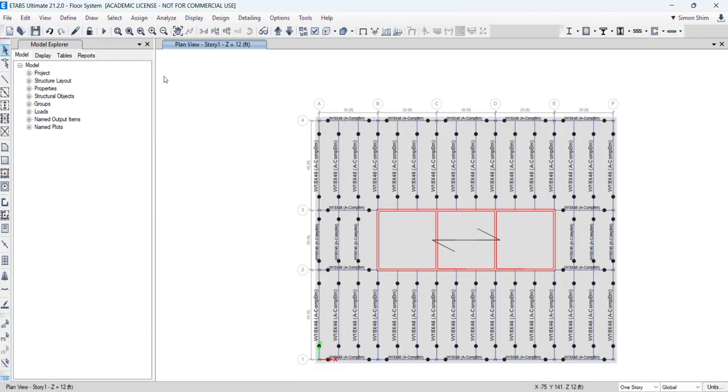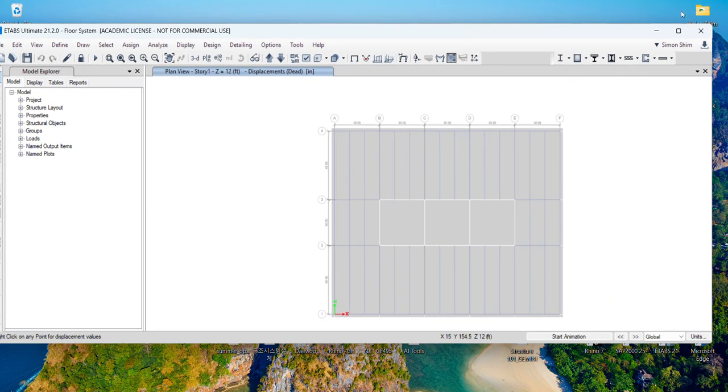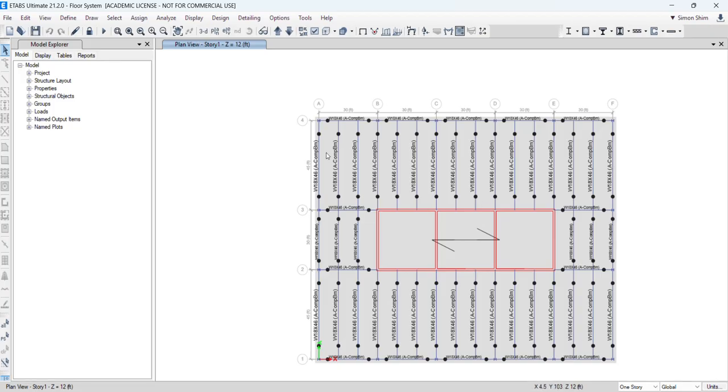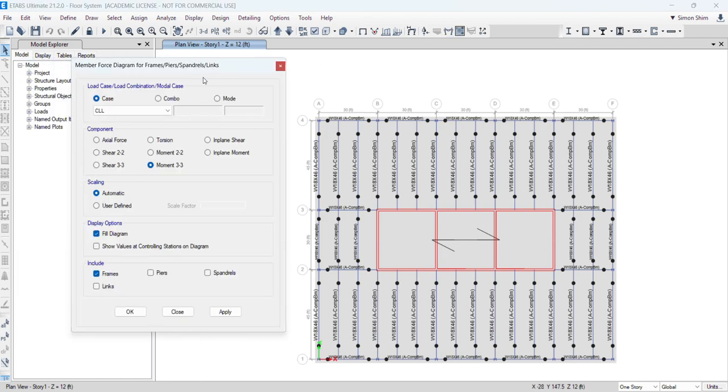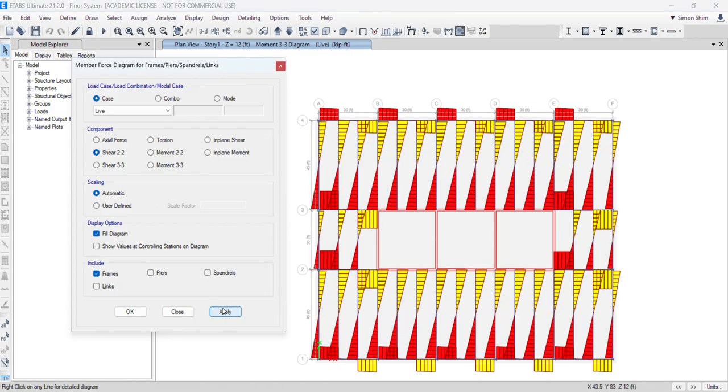All right, one thing I want to make sure of is that just drawing the geometry is not engineering. To me, it's the basic of the basic. You should have some sense of structure, right? And structural elements, including column, wall, girder and beams. But assume that you complete it, always, I said always, you need to check the forces. So based upon your input, dead, live, whatever the case is, just check the moment diagram and shear force diagram.